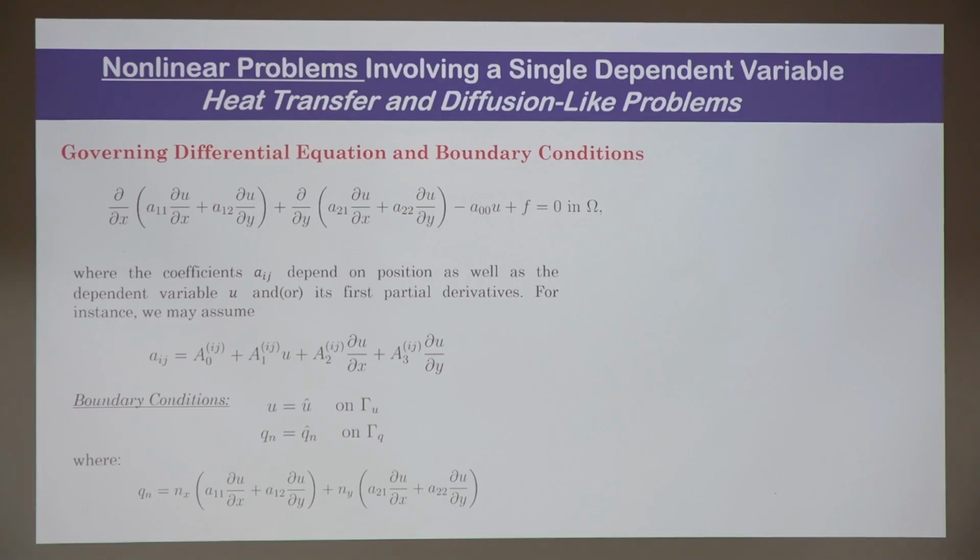And you might say, what about finite volume? Well, if you really try to do everything like what I'm doing in dual mesh, you can show it will give you the same solution. But when you replace with the derivatives, there would be discrepancies because you're not supposed to replace the secondary variables with the derivative Taylor series expansion.